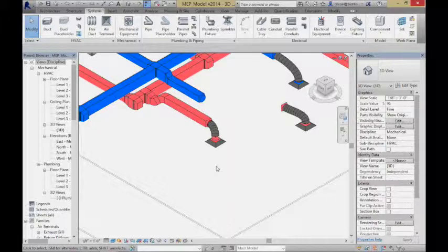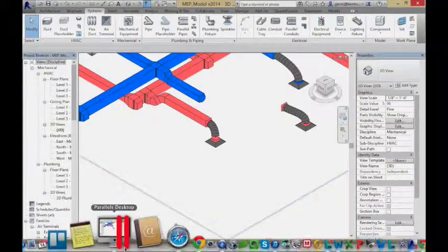So we will continue with this notion of HVAC systems and how we design these things next time. But that's the general principle: if you start thinking about the air changes, we ultimately determine how many terminals we need to supply that.